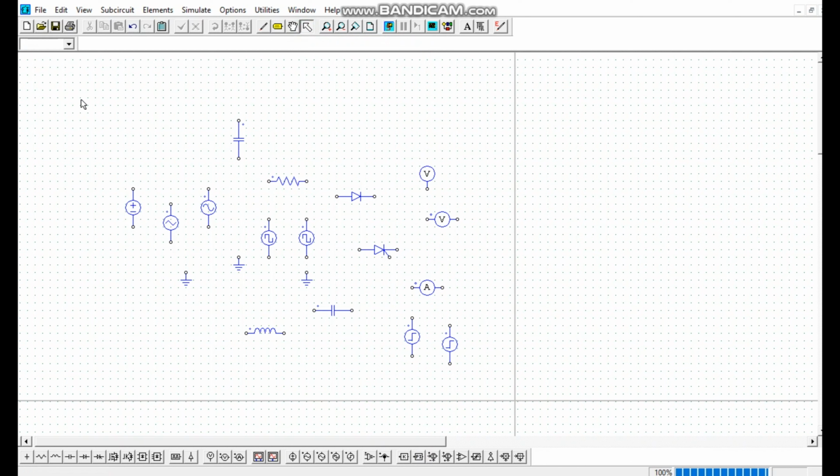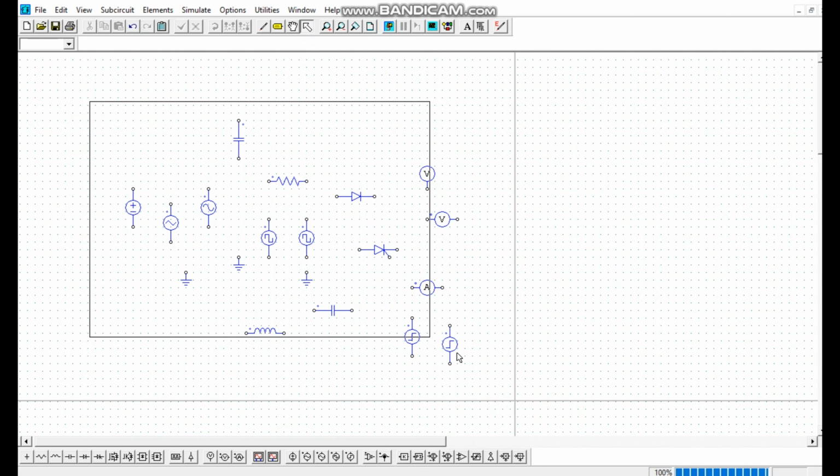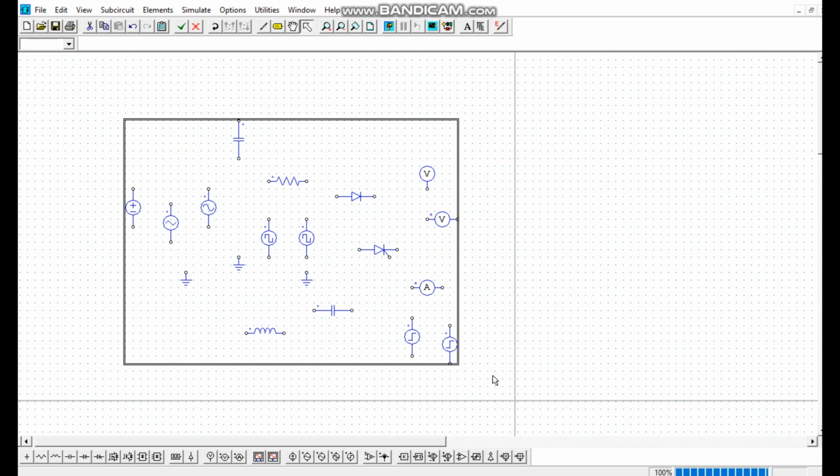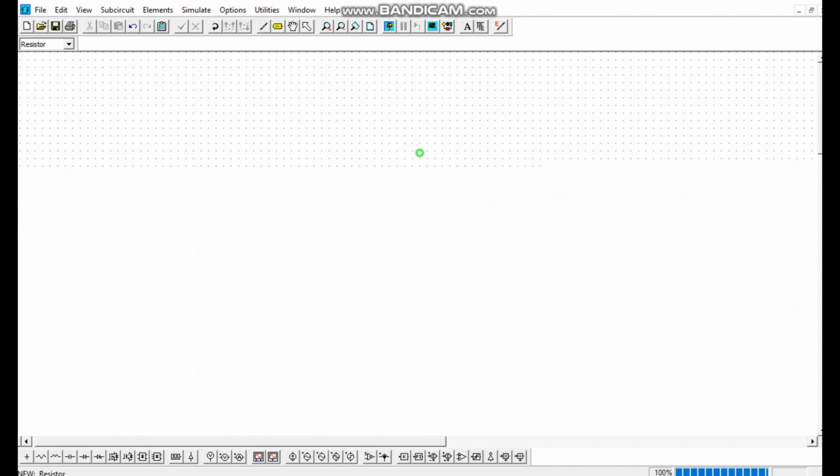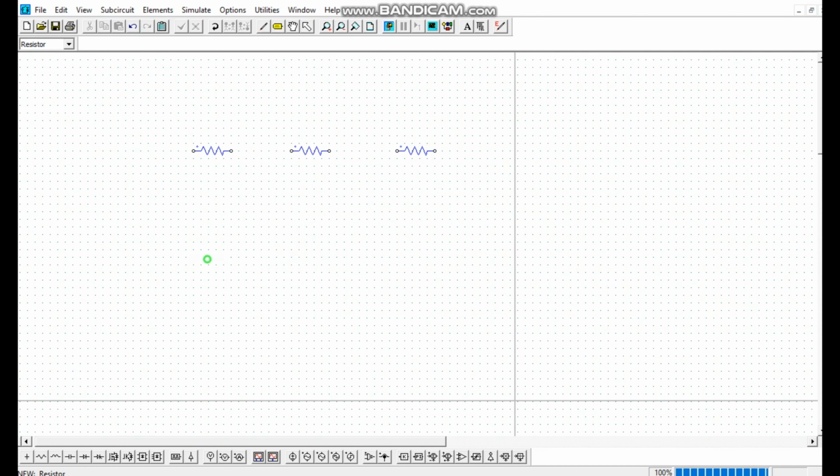Basically, if we want to see the theoretical value, we can see what voltage source is being used. We can clear the shape by selecting the component and using the keyboard delete key to delete it. Then we design a circuit by placing 6 resistors in series, then we use a DC voltage source, and we measure the current in this circuit.